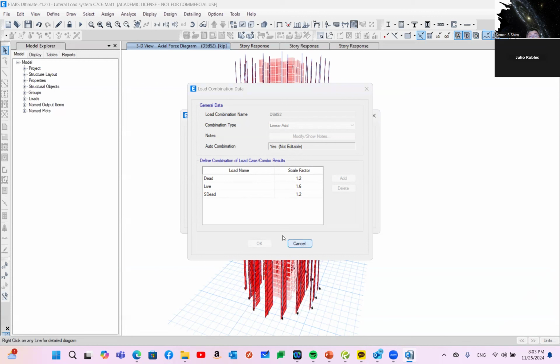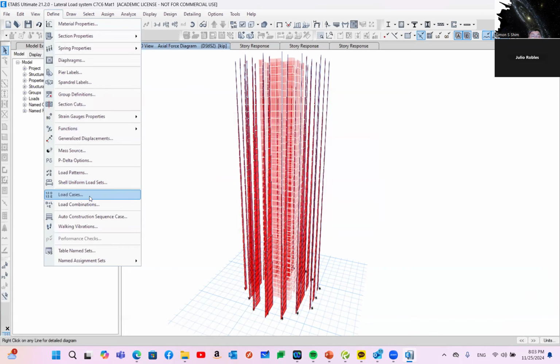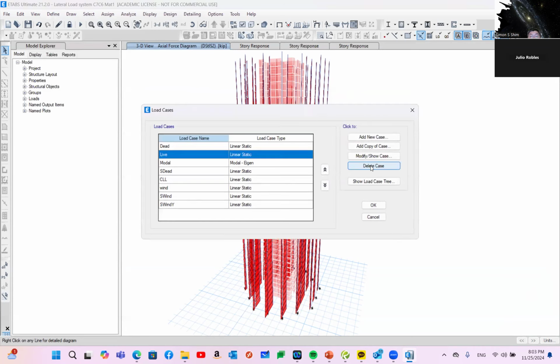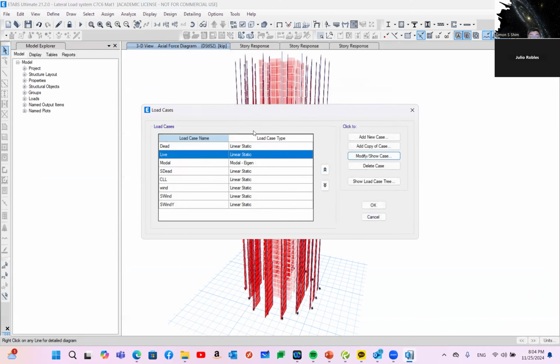Good. So just in case of live load, you can use live load reductions. Typically I apply the reduction factor right here. Oh, we already applied 0.5. Okay, good. So this is plus minus okay, but we can use up to 0.4. But since for some upper columns it cannot be 0.4.